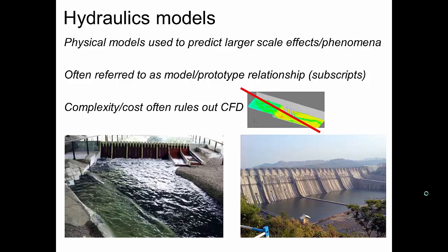So actually when it came to early season testing, they found out the drag was much higher, therefore their fuel consumption was higher, and they'd undersized their fuel tanks. So for the first 5 or 6 races of the season, the team had to retire before the end of each race because they were running out of fuel. So again, had they done wind tunnel testing with a scale model, or you can even fit a full scale car in some wind tunnels, they would have found this out. So over-reliance on numerical models.